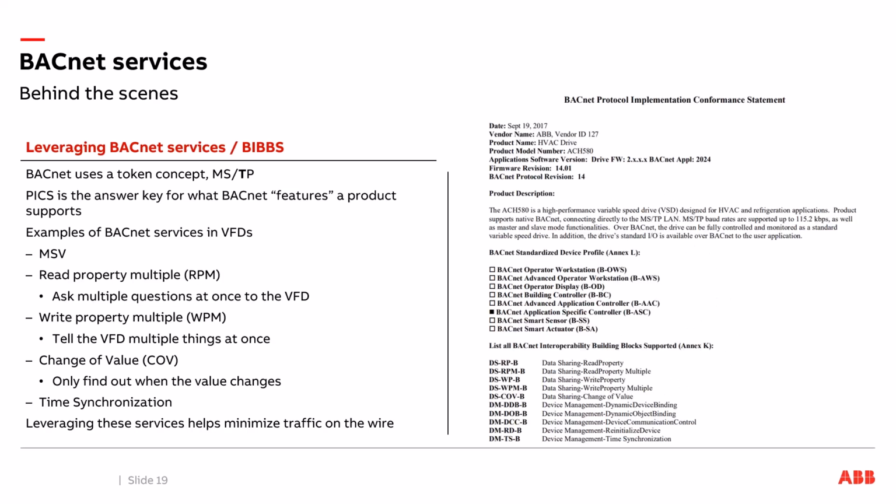Other items about BACnet, there's the PICS, the protocol implementation conformance statement. I referenced that earlier. It basically tells you what aspects of BACnet a particular product supports. So that happens to be a screenshot of the ACH580 PICS document there. So the multi-state value, that's an example of something you can support. I explained that one in the previous slide.